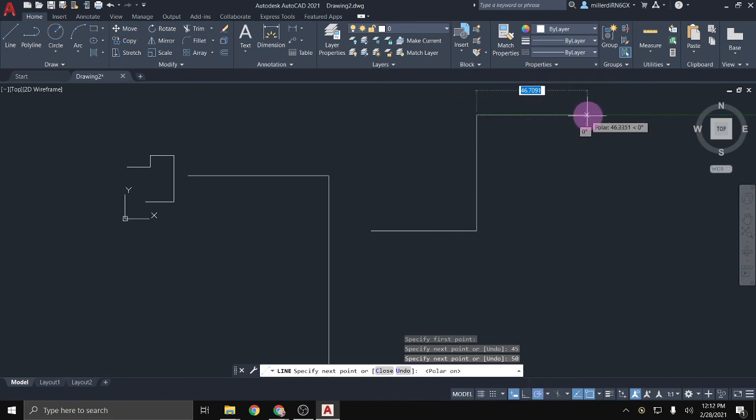I personally prefer polar tracking, but like I said, if I think my cursor is exactly where I need it to be, and then it moves slightly, and I go to start typing my distance, I can't correct it, which would be annoying with a mouse on a flat surface. As long as I just know that it's in the right area, I should be okay. What I would have to do instead is hit escape, correct my mouse, then type my distance, enter.